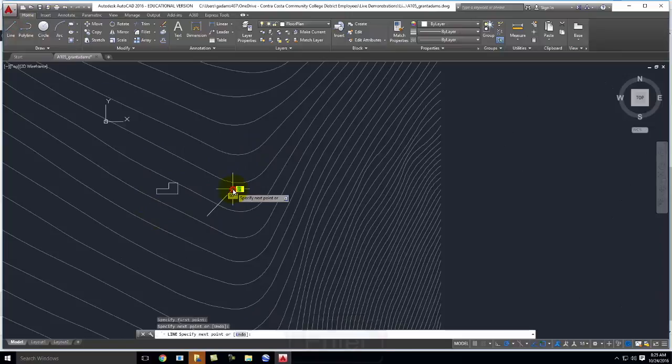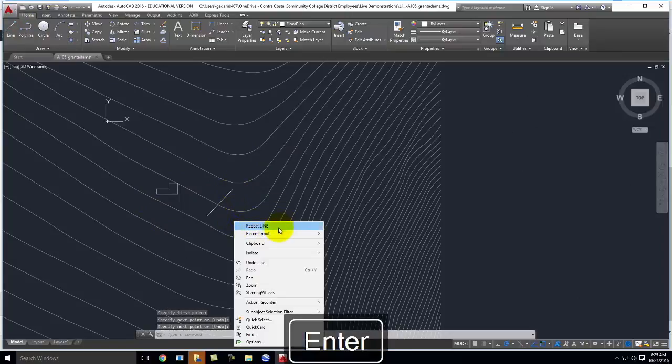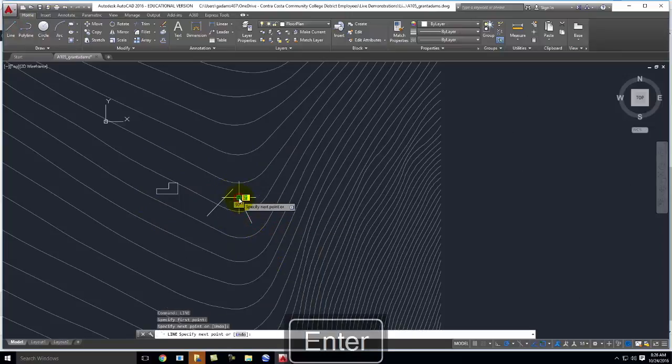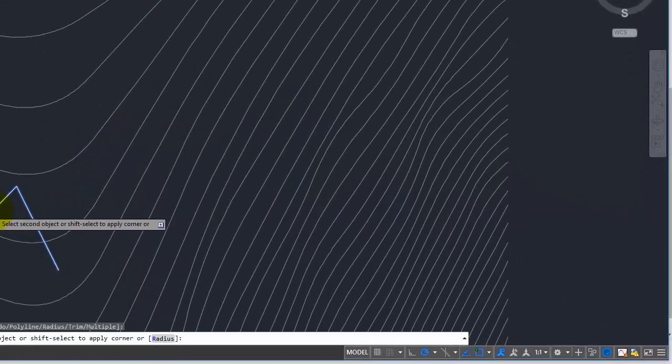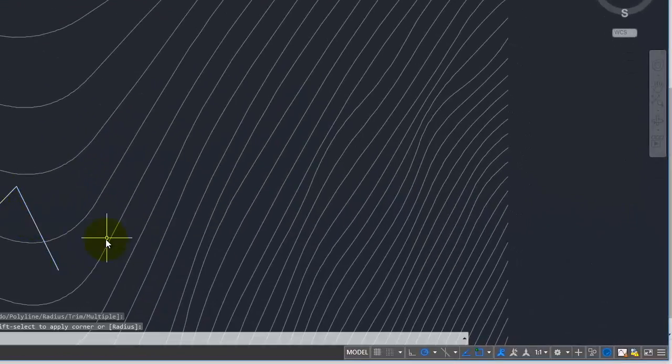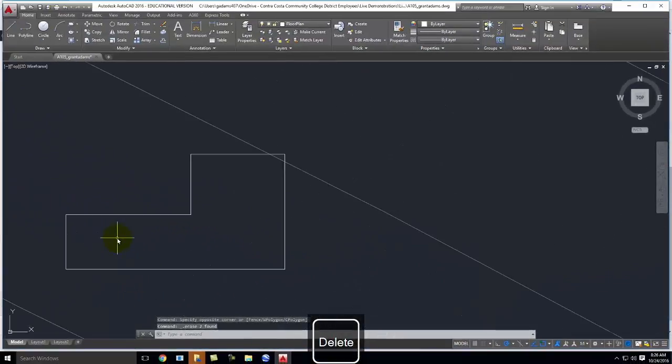Let's say I had this line and I had this line, and I wanted those two lines to come together. I could use the fillet command and connect essentially that to that. Okay? It's a really cheater way of doing things. I use this all the time in CAD. So I like to point that out early because it's a trick. Okay? So that's a fillet.